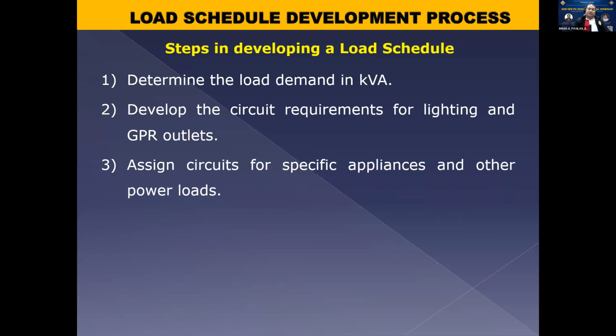Next, once we are done with the lighting and outlets, we need to assign the circuits for specific appliances and other power loads such as refrigerators, water pumps, air conditioning units, heaters, dryers, etc. Yung mga malalaking loads. That's the third step.